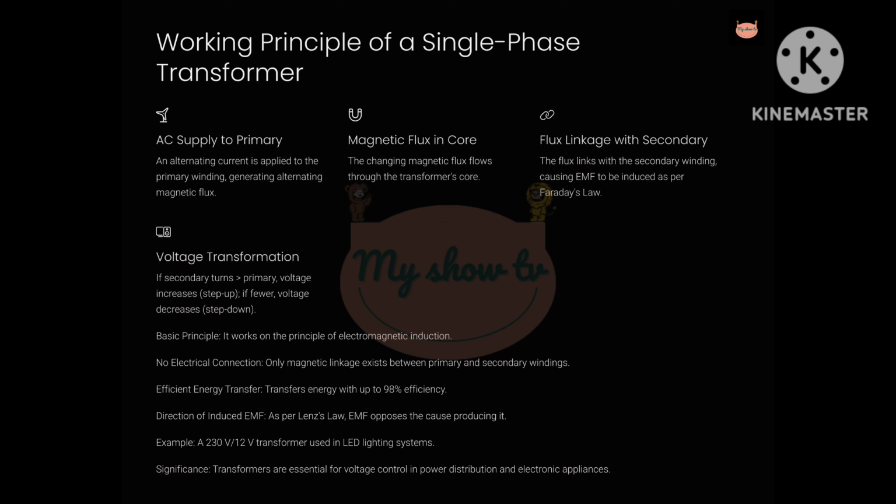Now let's understand how a transformer works. 1. The transformer operates on the principle of mutual induction. This means when the magnetic field created by one coil, primary, varies, it induces a voltage in the other coil, secondary, placed nearby. 2. When alternating current, AC, is supplied to the primary winding, it produces a changing magnetic field.